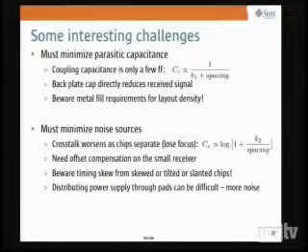Noise, certainly by having clever layout, I can minimize or mitigate the effects of noise, but it's still there. So I better make sure that as I pull apart and lose focus, I have some sort of packaging scheme that prevents me from moving too far apart and having signal minus noise become zero. One thing you can do for this is offset compensation, but you've got to be careful, because offset compensation often adds capacitance to the input of a sense amp, and any capacitance, of course, lowers your voltage swing. So there's a nice interplay of energy optimality and noise performance for these circuits.